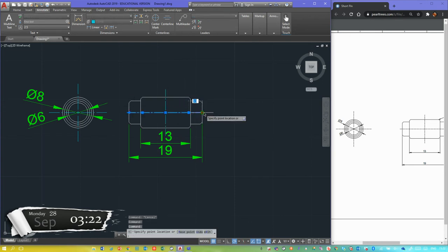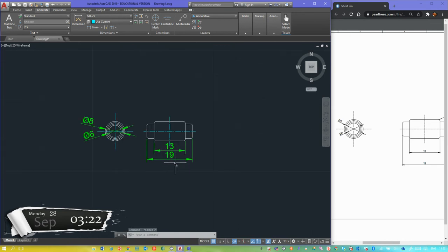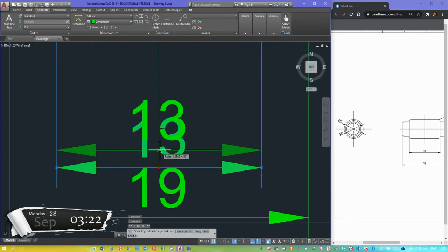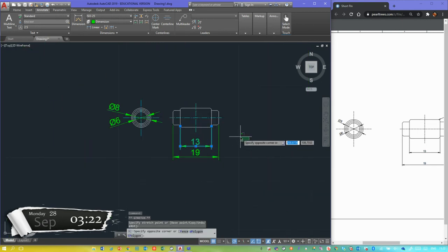Then we just select that and move it a little bit out and a little bit out, because what we should see with the center line is that it comes just past the thing that we're indicating it's the center of. Now, looking down here, we've got this center line clashing with those dimensions. So I'm just going to press Escape, click on the dimension, and drag that down. Press Escape again, we don't want to select them both. Just drag that. Let's zoom in. There we go. There, okay, and there we are.